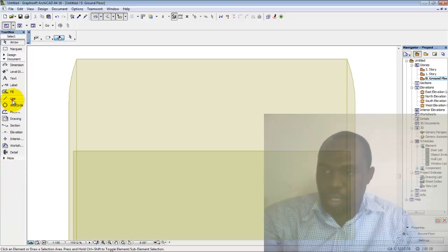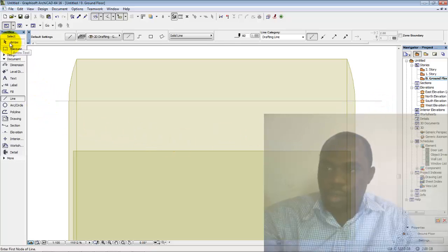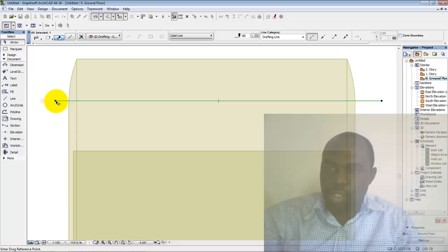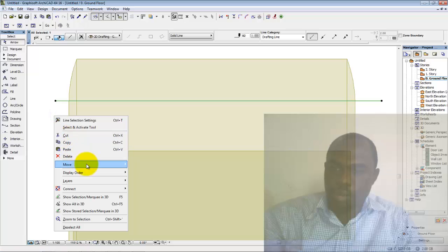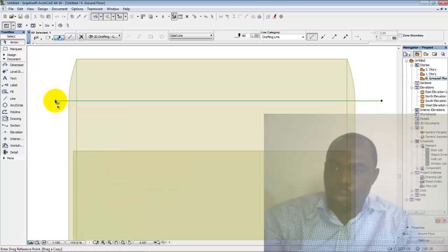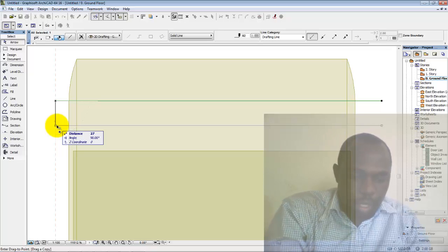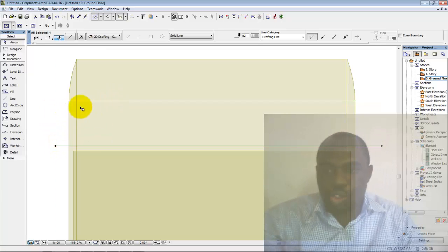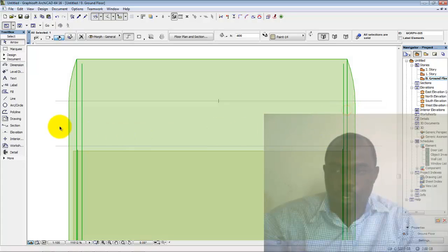Use a line tool, draw a line across, just to give us a guideline. You can offset about, you can do Control D, Control Shift D, drag a copy as an offset from the main line that we just drew. Then we're going to type in about 50, enter. So we're going to draw our pattern for the thread within this space, within this line and this line